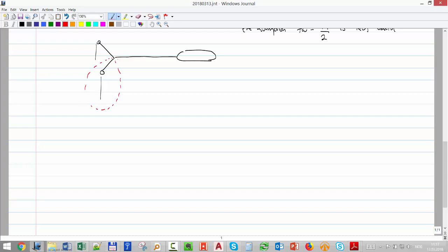Okay, so I'm going to divide that system in three parts. First, let's make the assumption of an open choke. I'm going to take a system called 1, that will be my well 1. I'm going to take a system called 2 all the way to the junction, well 2. And then I'm going to take a third system, which is just the pipeline. And I'm going to plot, as seen from each one of these subsystems, the pressure at the junction. How does it look depending on the rate?